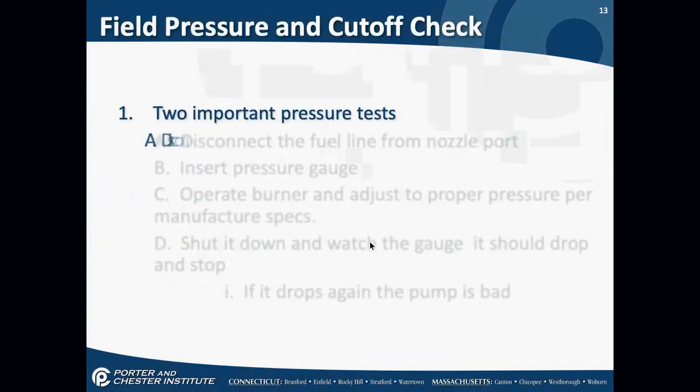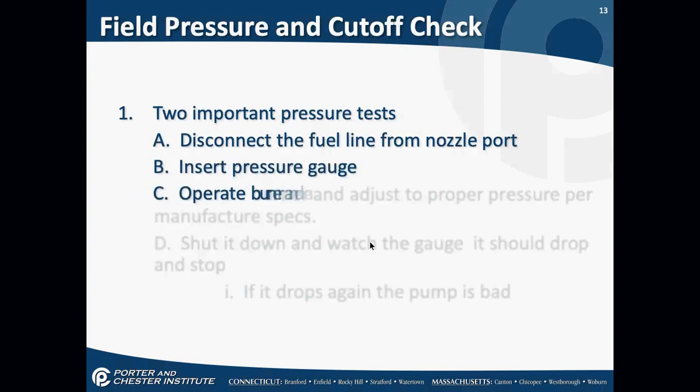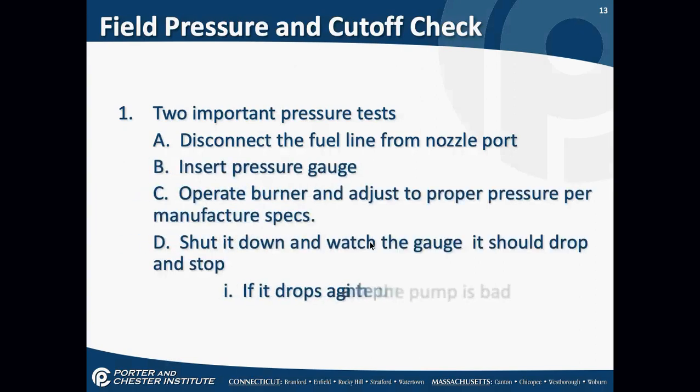There are 2 very important pressure tests that we do want people to realize. You're going to practice this stuff in the lab, but I wanted to go over it just to make sure we've gone over it. There are 2 important pressure tests: a field pressure and a cutoff check. Oil burner technicians carry, and most often your company will supply this to you, 2 gauges. One's a pressure gauge and one's a vacuum gauge, specifically designed for oil.